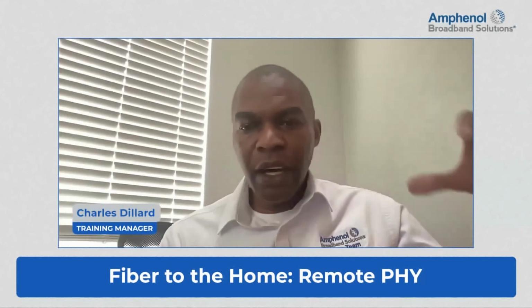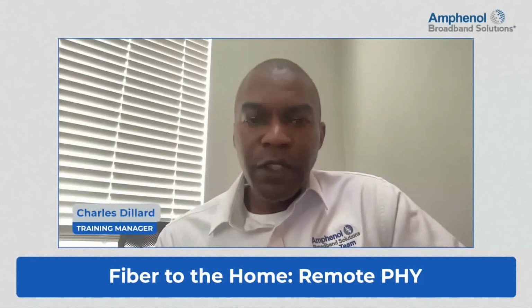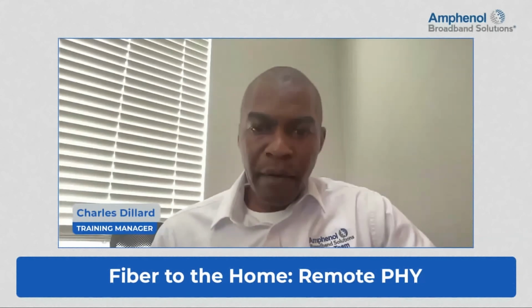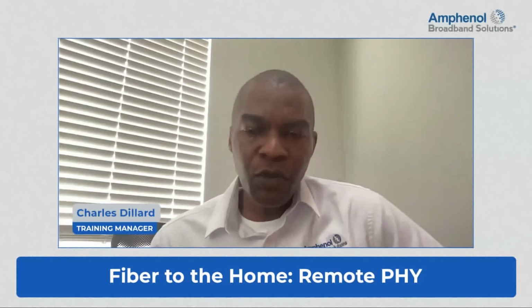Because now, with a digital fiber link and an Ethernet switch in the hub side or head end, we need to understand Ethernet and Ethernet testing. Currently, if you're in a system where you have enterprise technicians who go out to businesses and install fiber internet access circuits, they are familiar with some of the RFC testing, such as 2544. Now those types of testing will need to be leveraged by other individuals, such as maintenance technicians, as well.